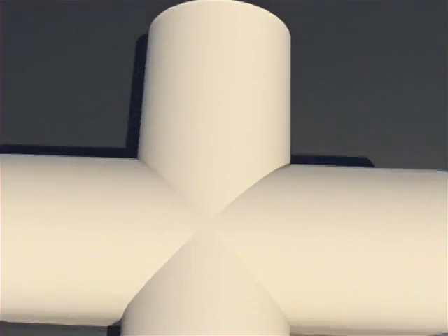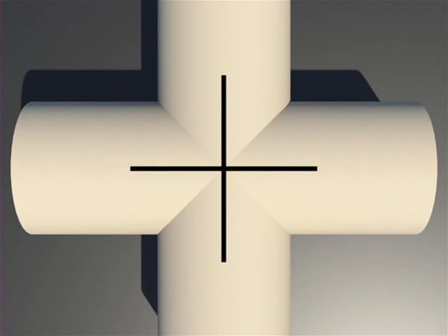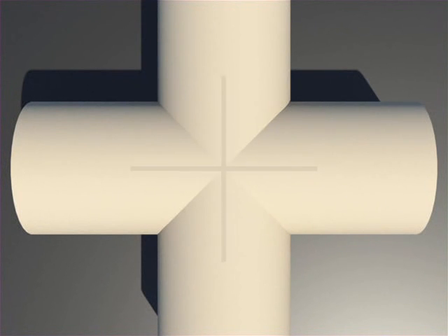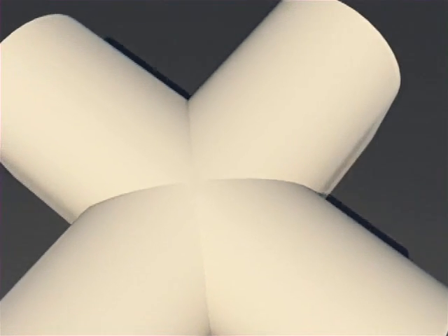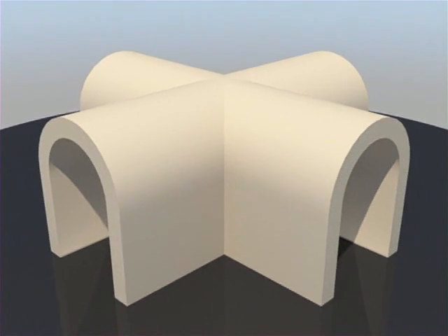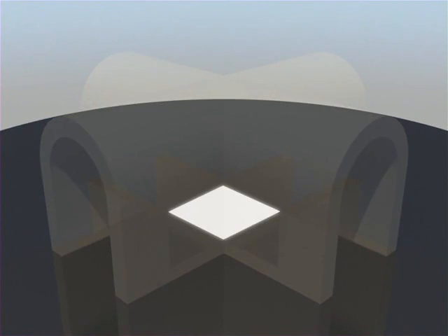Perhaps the most impressive aspect of the structure is the expanse of groined vaulting that forms the ceiling. Now, a groined vault is formed by intersecting 2 barrel vaults at right angles to each other, like this. The use of groined vaulting in ceilings resulted in the subdivision of the interior space into square or rectangular bays when viewed from above. Each transverse vault corresponds to 1 bay.